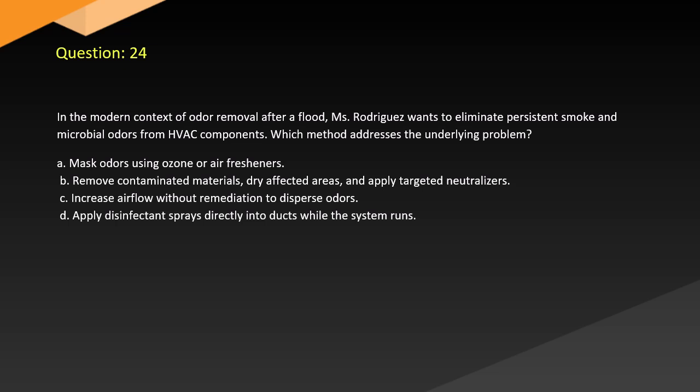Question 24. In the modern context of odor removal after a flood, Rodriguez wants to eliminate persistent smoke and microbial odors from HVAC components. Which method addresses the underlying problem? A. Mask odors using ozone or air fresheners. B. Remove contaminated materials, dry affected areas, and apply targeted neutralizers. C. Increase airflow without remediation to disperse odors. D. Apply disinfectant sprays directly into ducts while the system runs.